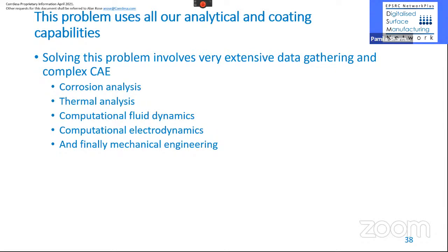Right. Well, there are two ways to handle this problem. You may remember that video that we had of how you do masking. You can mask an area, and chemically or mechanically strip the damaged anodize from within that area.